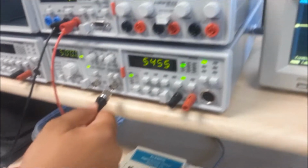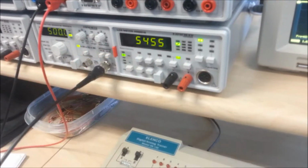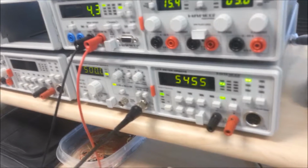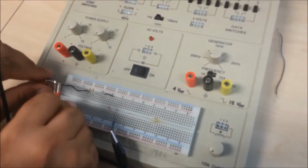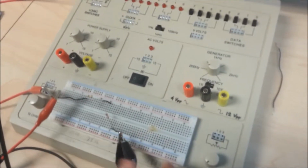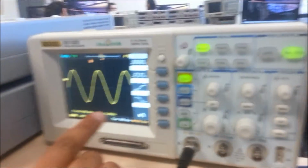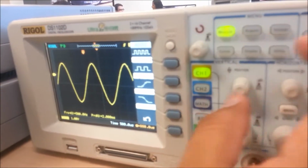We go to our function generator. It's our BNC connection. Make sure it's on the 50 ohm output. Again, 500 hertz, because that's what we came up with for our frequency, positive to positive and negative to negative. And you can see that's your VRMS. Here on your oscilloscope are your peak-to-peak values.